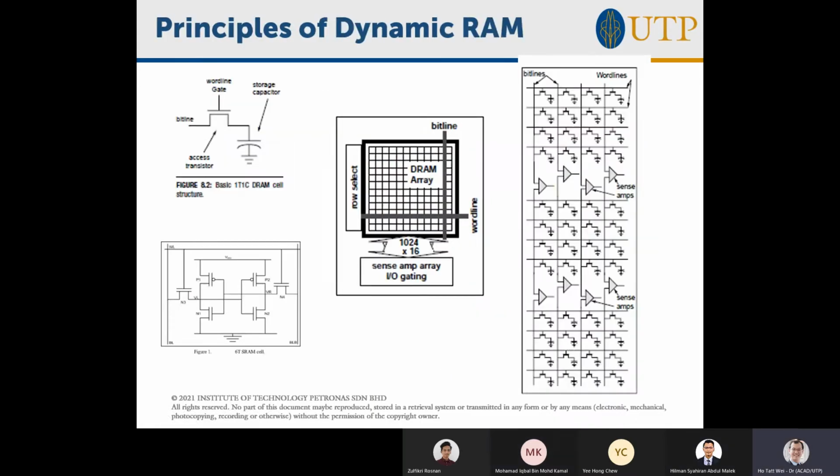Yes. Okay, great job. So that's why you need a word line and you need a bit line, because the bit line is everything in the column. The word line is everything in the row. So the way you access this is you turn on everything in the row, the word line. So all the bits in the row are going to go to all these amplifiers. The whole row, all the bits are being read out to the amplifiers. And then the column choice, the address of the column, will choose a multiplexer. One of these bits only will go out. Okay.